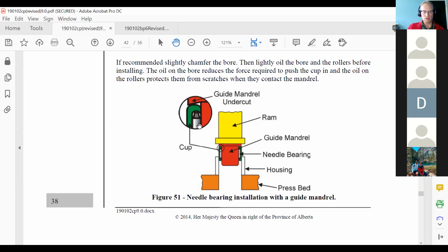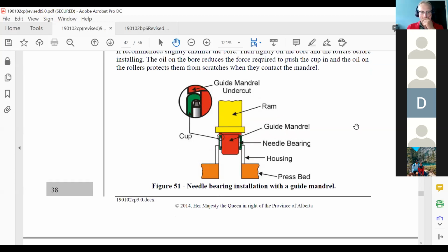None of these needles are going to fall down, or if they do, you pick them back up, because if you try driving the trunnion in there, then it's going to, I think you said it broke the needle, and that's absolutely, the needle will break. Sometimes they lay down flat in the housing, and then the trunnion won't go in all the way, and you're fighting, thinking, what the heck is going on? That's what happened. The needle fell into the bottom and I broke it.